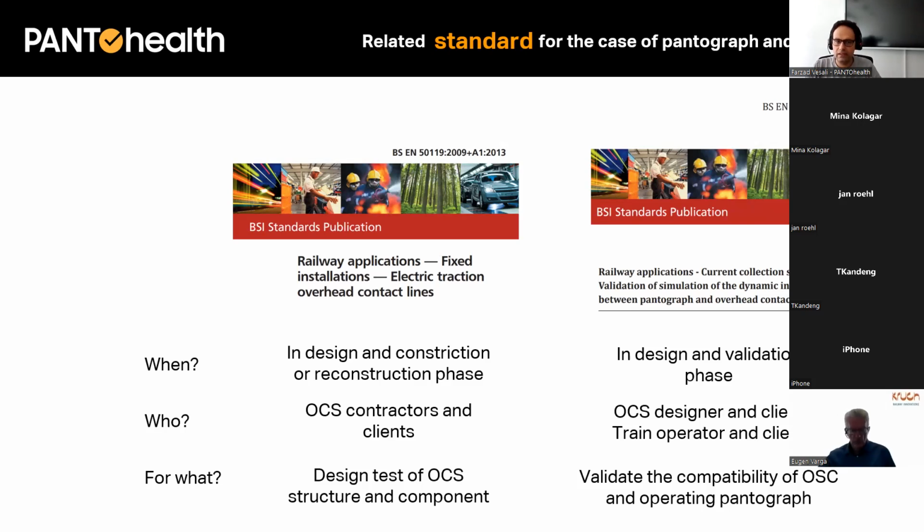For example, in terms of pantograph and catenary, we have a quite important standard called EN 50119, which I guess Jan is really into. It's a railway application, fixed installation, electric traction overhead contact line in the design and construction or reconstruction phase of the overhead contact line. You need this standard. Normally, OCS contractors like Jan and clients use this standard to design and also test OCS structure and components. But another important standard is EN 50318.